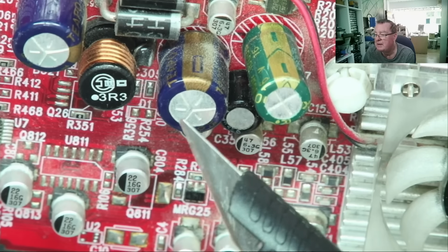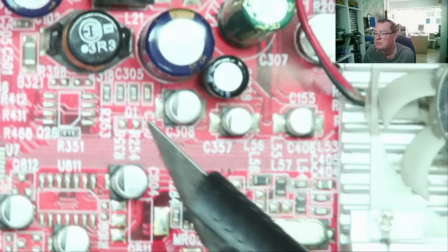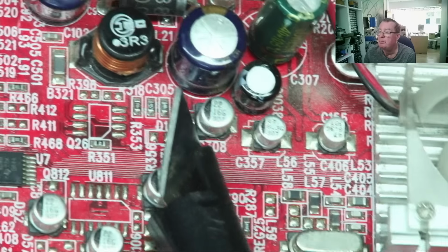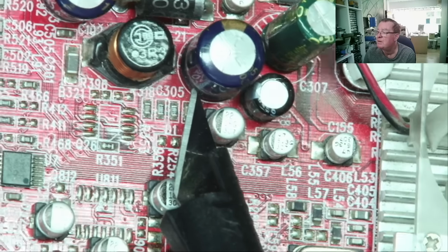This is a capacitor that is failing, and quite often they're worse than that. You will see a brownish colour residue because the electrolyte has leaked out, and sometimes it leaks from the bottom, so there's a rubber bung in the bottom where the leads go in, and that fails and the capacitor leaks out onto the PCB.